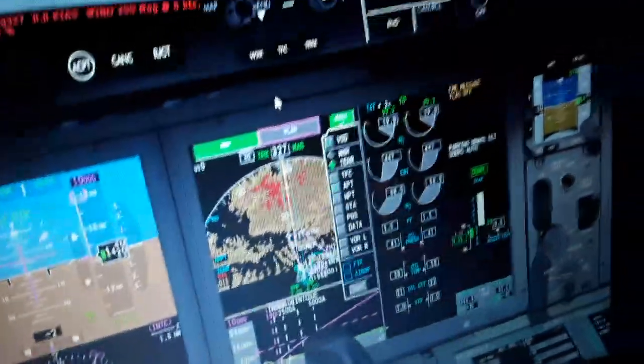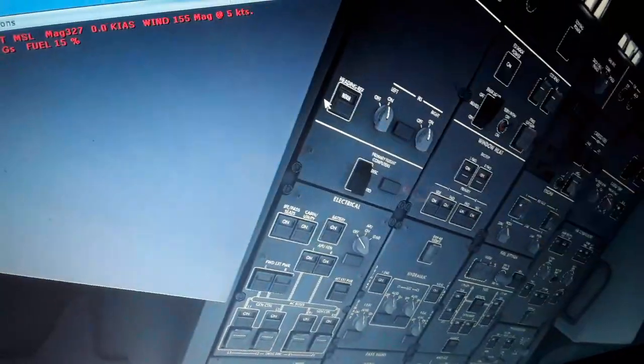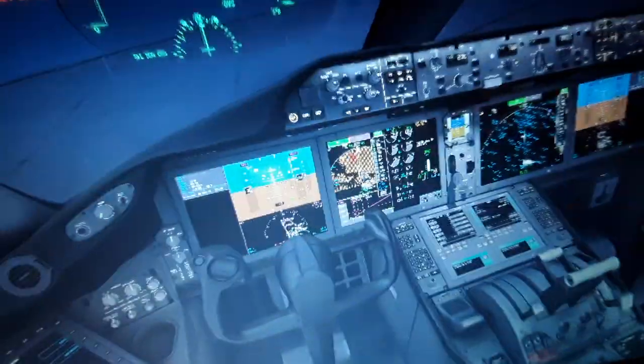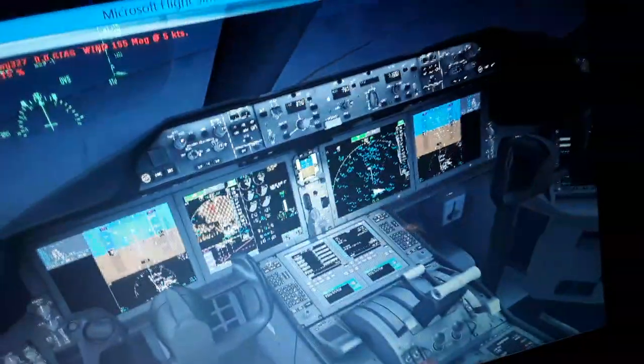So this is all the things we need to know from the flight management computer. Inputs, we have the air data computer. Over here it displays the pitot static and pitot dynamic, airspeed and altitude, and GPS position, laser gyroscopes, magnetic north pole, all their data you see. Angle of attack as we fly. We have also the engines, the FADEC control. The engines, we have the FADEC. The FADECs are the full authority electronic control computers.